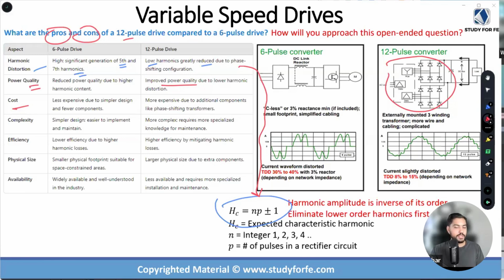Depending on the size, the configuration, it is not always the actual VFD that is expensive, right? In order to make use of this VFD that offers 12 pulse conversion, you actually have to have a dual winding transformer, right? You have to have a secondary and a tertiary. The cost of this transformer itself can be a big element. All right. So you have to have additional components, and then obviously more labor, more material cost, and whatnot.